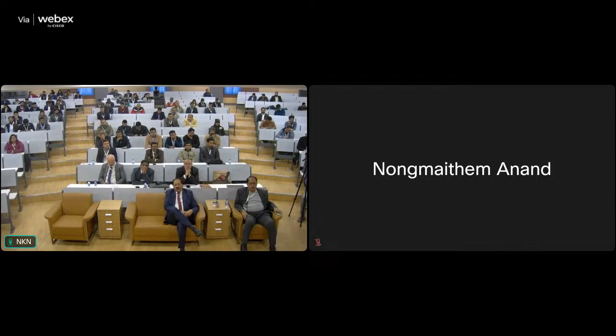And you know that before the rock bolt installation, just after the excavation, we have to have the first layer of shotcrete, which is called the sealing shotcrete. And this should be at least 30 to 50 millimeter, right? So that means with the understanding that there will be improvement in the rock mass quality around the opening, you may not require the second layer of the shotcrete if you have proper thickness of the sealing shotcrete. So this is what I want to discuss. I have just concentrated on one point.